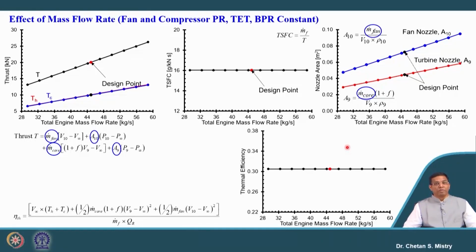Okay. So, in order to increase the thrust, you can go with the increase of mass flow rate, but somewhere you need to compromise in terms of fuel consumption and efficiency. Maybe in order to handle that, you need to have a larger size engine, maybe the entry diameter needs to be larger, and at the same time the exit dimension also needs to be larger. So, that is what will decide the mass flow rate parameter. Now, this is giving an idea about our ground condition.